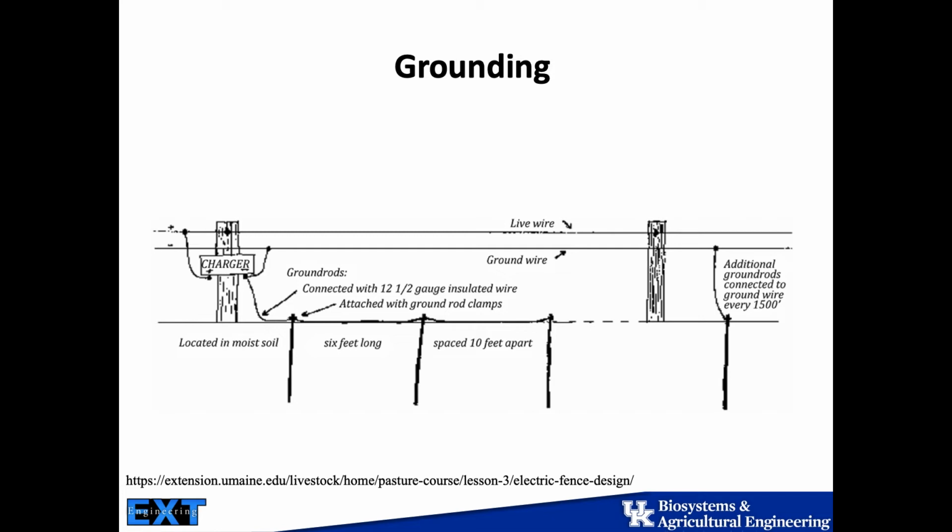So there is flexibility in a solar box in the sense that you can move it, but you still need to somehow ground it. And if it's rocky soil or somewhere that doesn't get a good ground anyway, you need to put the ground rods in, and it's just a lot of work. So I think this is one of those catch-22s: the solar box gives you flexibility, but at the same time, the solar box creates challenges if you don't get the ground rods properly grounded.